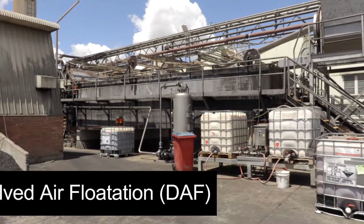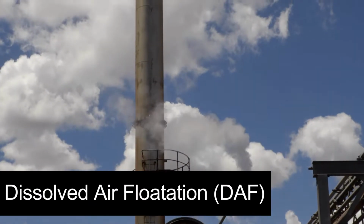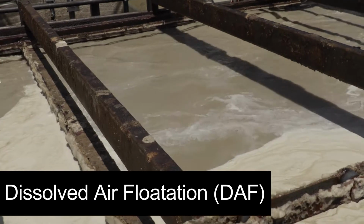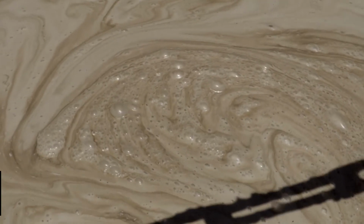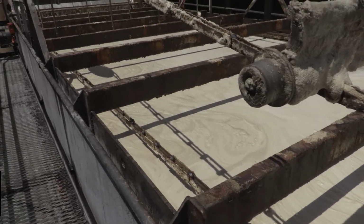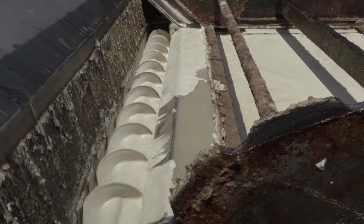A dissolved air flotation, or DAF, is a common sight in Australian meat plants. DAFs inject a high-pressure stream of liquid containing high levels of dissolved air into the raw wastewater stream. The dissolved air forms a mass of very fine air bubbles. These bubbles attach to particles and fat globules and lift them to the surface, where they form a float of aerated material. The floating material is scraped off for disposal or reprocessing, and the cleaner water underneath is discharged.